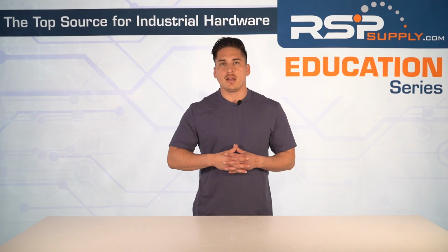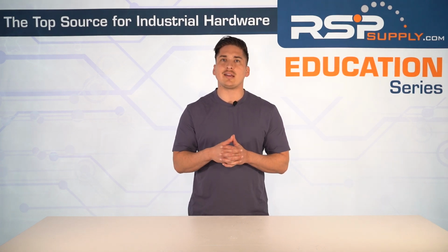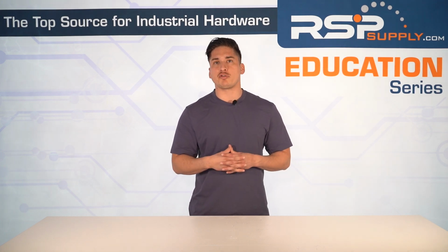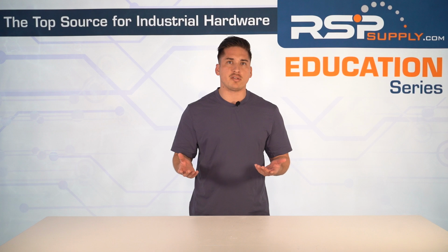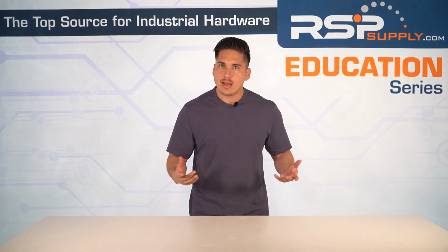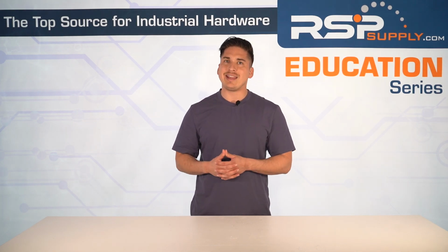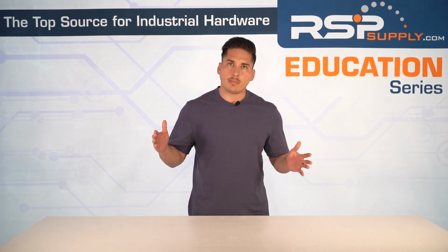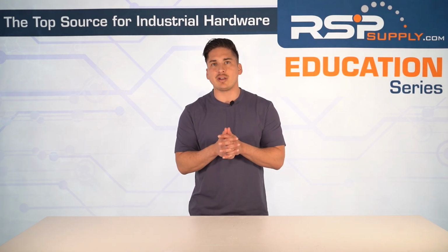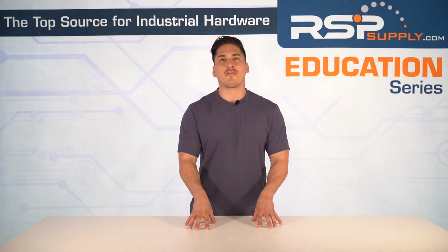Despite being older tech, field bus still holds value in legacy systems in areas where noise immunity and simplicity are key. So today we've explored the backbone of industrial communication, which is network topologies, from simple bus layouts to more robust mesh networks. Each structure plays a role in how your system performs when it comes to reliability, speed, cost, and scalability. We also touched on the importance of redundancy and fault tolerance because in automation, downtime just isn't an option. And finally, we compared industrial Ethernet with field bus,